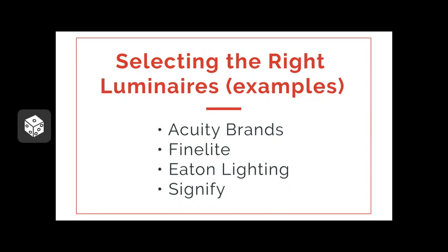For your class projects, you may need to go and select electric lighting luminaires. And I just put down 4 companies that really have a huge variety of excellent solid state lighting luminaires. So I would encourage you to go to these websites and select luminaires first that are going to light the walls, graze the walls, and then light the ceiling. And then also look for some task lighting.